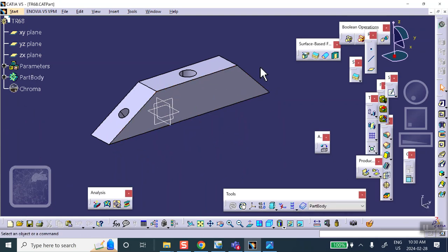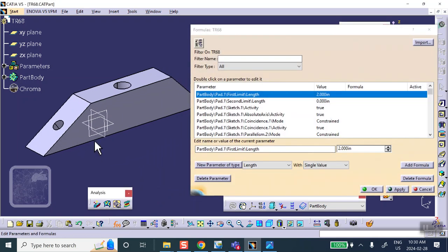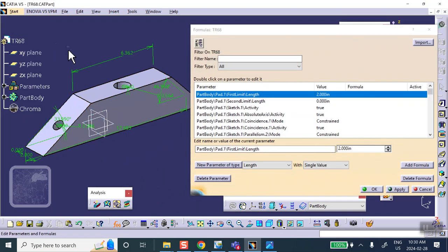And now we're going to rename stuff to make our job easier, because the design table, I want it on the top row to have stuff like this: serial number, material, L, B, etc. So let me rename the stuff. So f of x, click on the top.